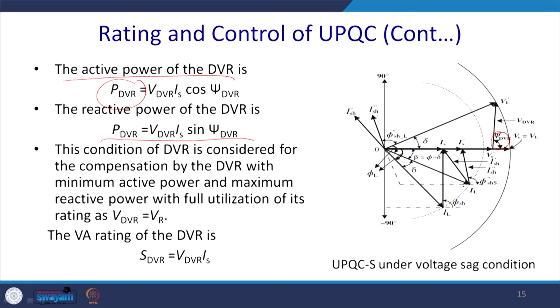Similarly, you had this value of Is, and you can apply this shunt compensation current at an angle, and it may be at a different psi, and thus you get a psi prime, and you get this injection and you get psi prime again. So, what the phasor says is that from this angle you can have a different value of psi compensation. So, you can play around with psi and the magnitude of the compensation current.